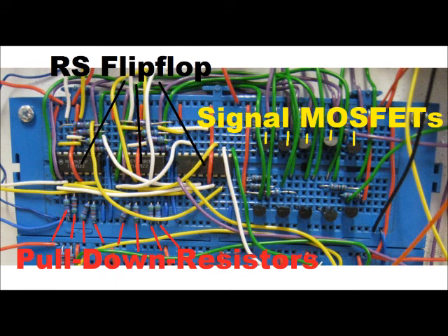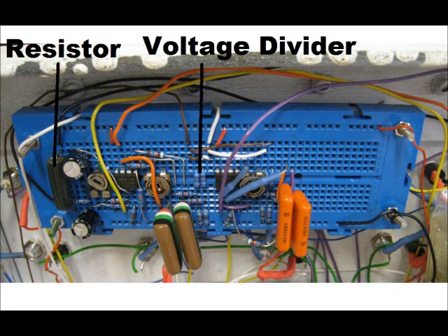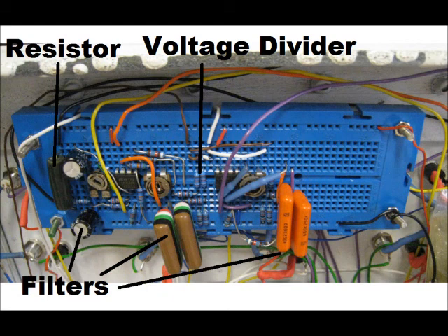These are the current and voltage measurement circuits. The current is measured by analyzing the voltage drop occurring at a defined resistor. The voltage applied at the motor is reduced by a voltage divider to reach a voltage lower than 5 volts. First, the signals are filtered due to the PWM frequency of 8 kHz. Then the signals are amplified by differential amplifiers to reach a defined output. This output is filtered again and then connected to the microcontroller ADC.